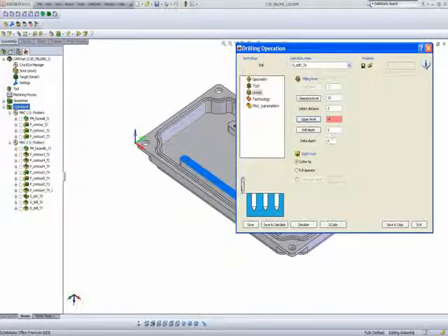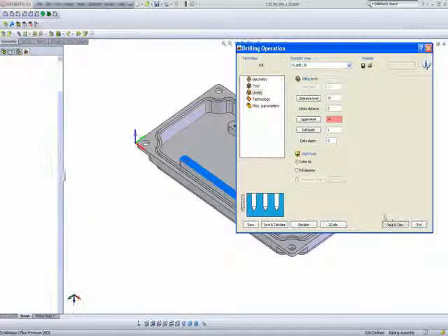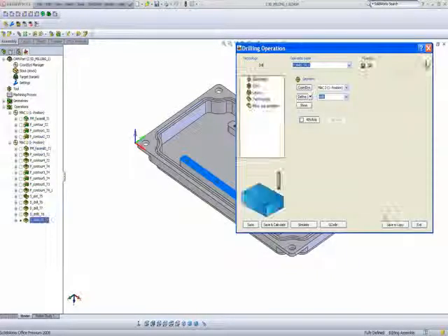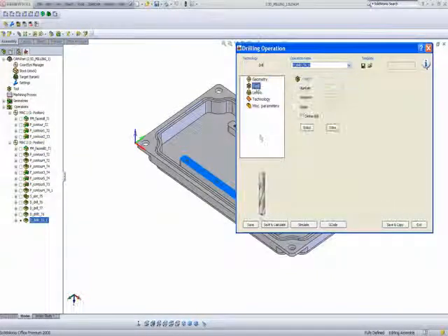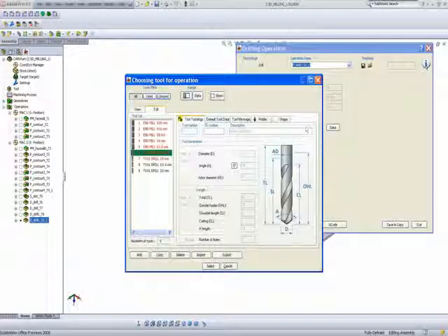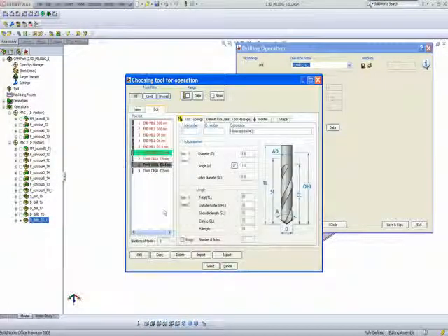But this time, instead of using my diameter value, I can also use a simple cutter tip option where the depth will be exactly what I tell it to go down to, and I'll tell it to go down exactly 1 millimeter. I'll simply do save and calculate and go to my next operation. Now my next operation, I'll change my tool to a 1.6 millimeter drill.